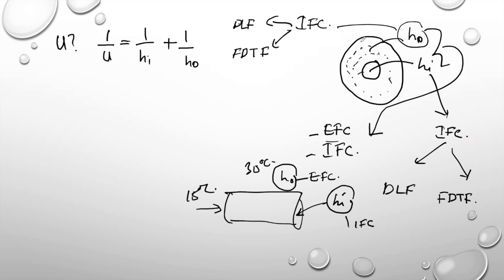So here we have a tube inside the tube. Therefore, this h_out is considered as internal. Okay, that's why for the double pipe heat exchanger, we will calculate the h value from the internal forced convection equation. So now we have to calculate what is h_i and what is h_out. So h_i is the heat transfer coefficient for the tube.